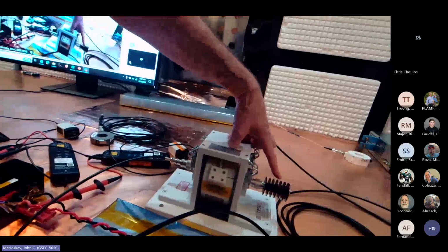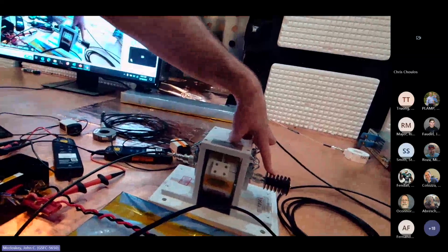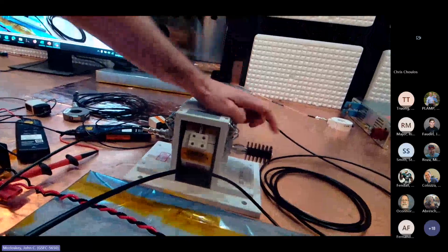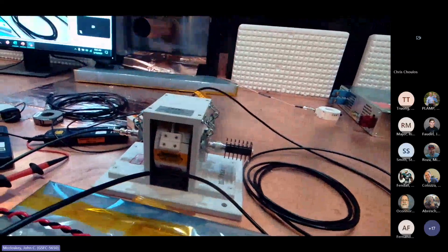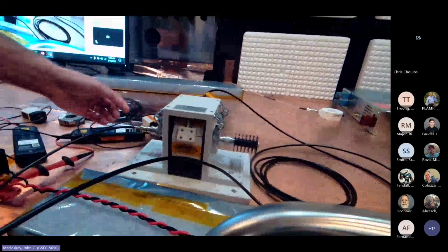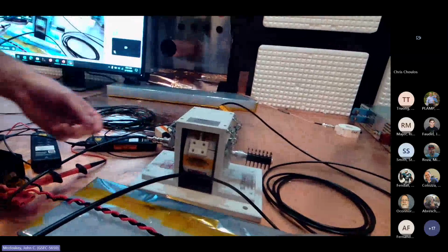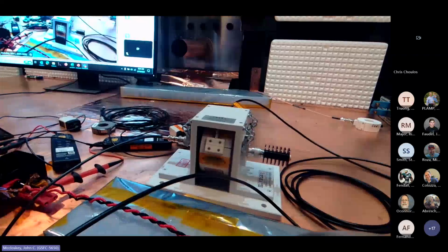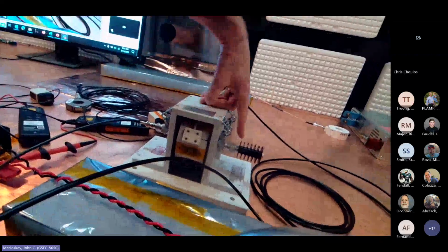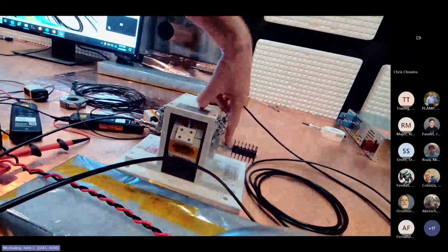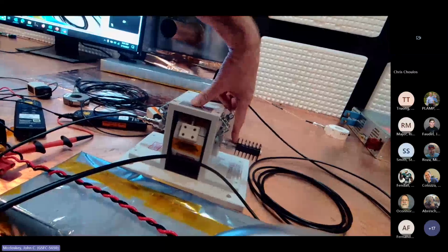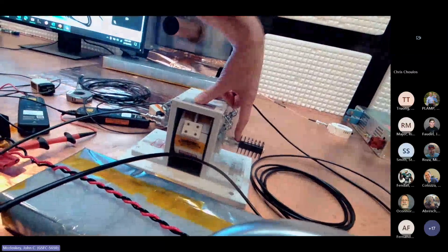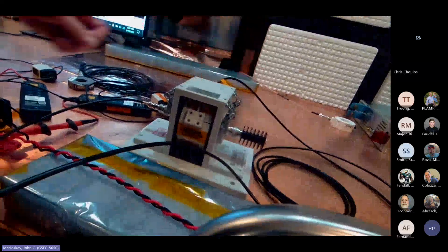For the powers that we're using, we probably don't necessarily need this high power load, but it's still good practice. You can see the heat sink on there. I can't read the power setting. That's probably a 50 watt terminator. Anyway, things to pay attention to with RF when you can be dissipating a fair amount of power. You don't want to put like a half watt terminator out here and then run watts through it. Then my fireside chat would become a little more literal, and so we're not going to go there.